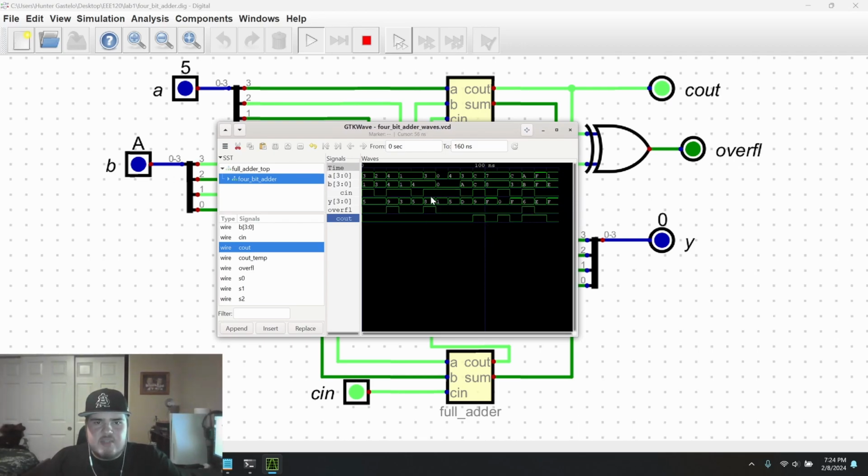So we see that in some cases, as in F plus F, or C plus C, or A plus B, they go too high in the binary range and revert back to 0 or a number that's lower than they're supposed to be. And we see that depending on which case, if it overflows, it's going to result in the binary representation of 2. If there's a carry out, it's going to represent in 1, but if there's an overflow and a carry out, it's going to represent in 3.